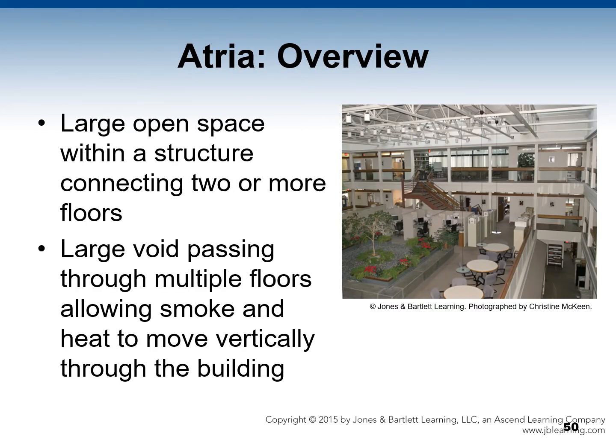Now let's talk about atria, or atriums, as people incorrectly use them, or atria is the plural for an atrium. With atria, this is a large open space within a structure connecting 2 or more floors. These are large voids that pass through multiple floors, allowing smoke and heat to move vertically through the building.